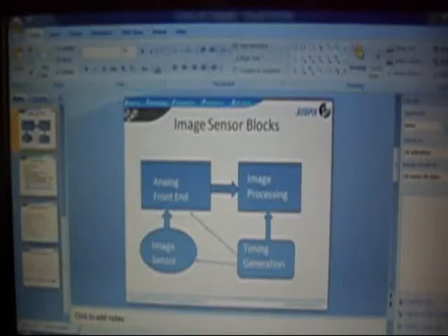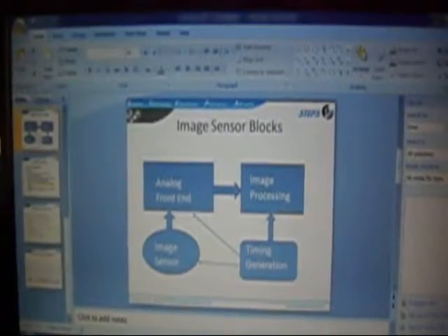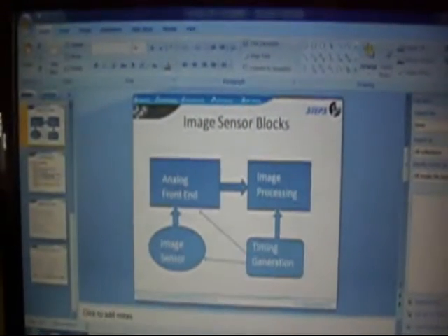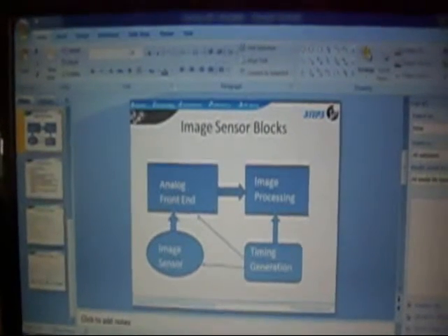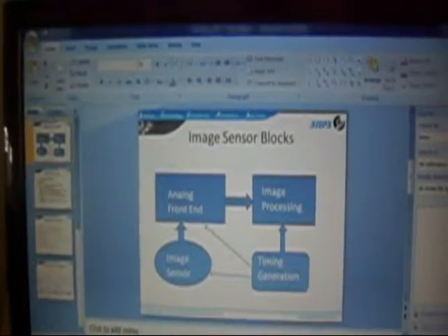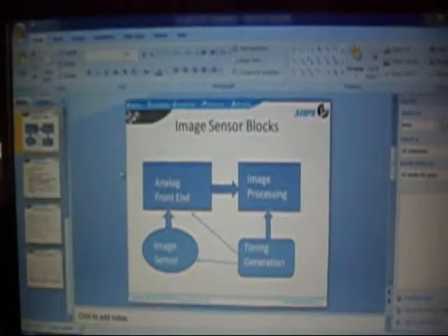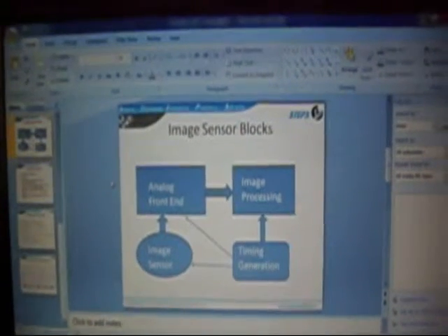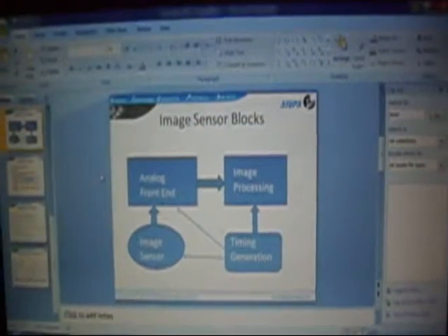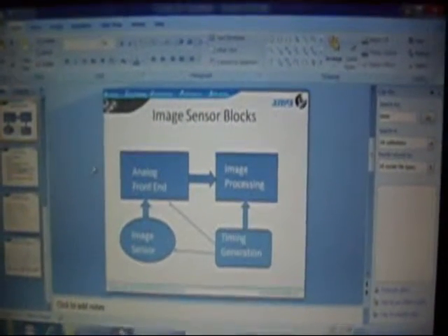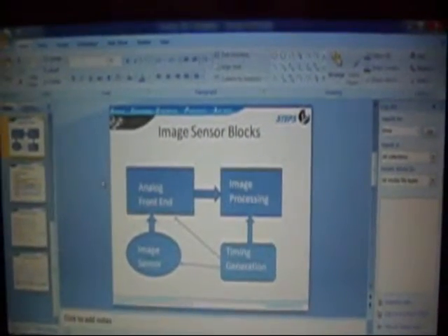The other features are high-speed image scanning and abnormality identification with its corresponding action. It could trigger a lot of actuators and valves, with independent scan control and a diagnostic network, multiple serial port interfaces such as UART, SPI and I2C, a USB on-the-go interface for data logging and connectivity as a device, data stream output, and micro DMA.